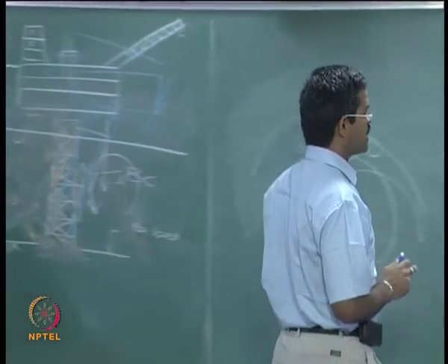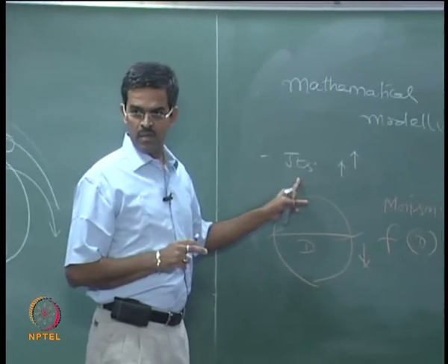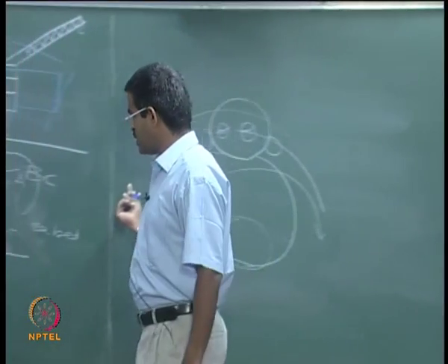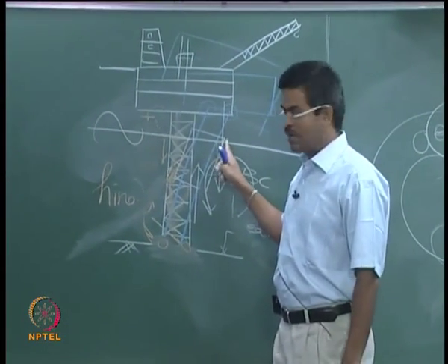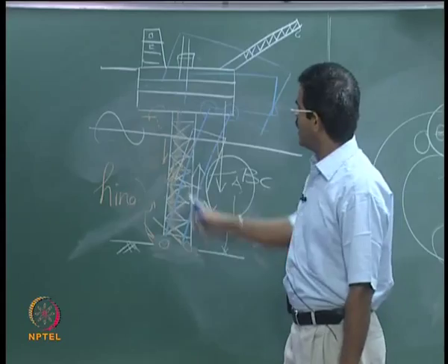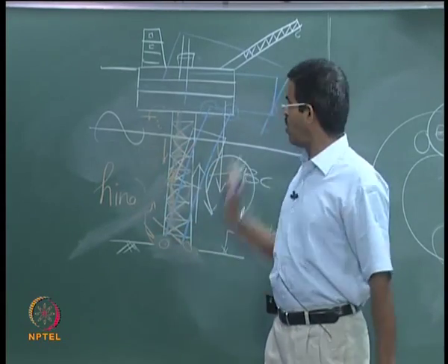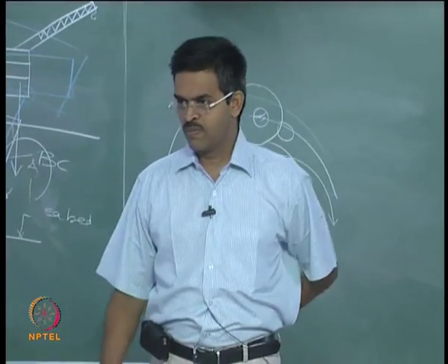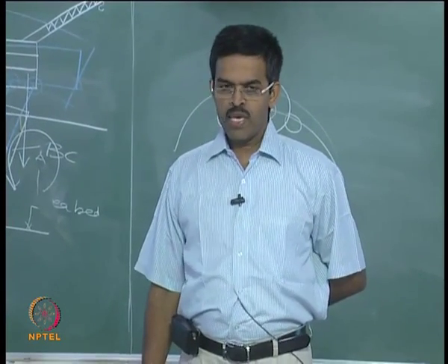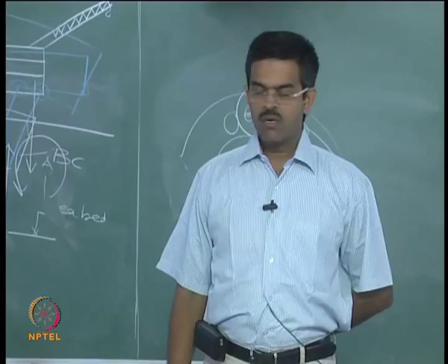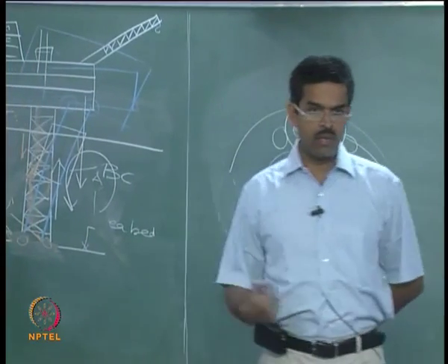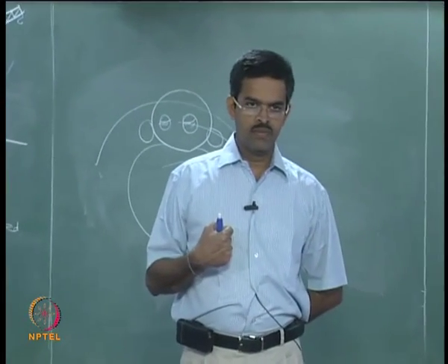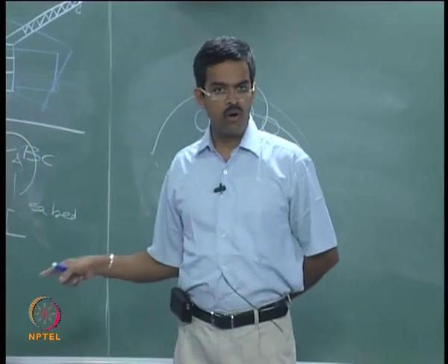So, when you introduce flexibility because of joints, you must compensate this flexibility by some other mechanism like a buoyancy chamber, like a mooring line, etc. All these towers in general are called compliant towers. Why was compliancy introduced? Because I want less force to be attracted on the member, because I want to use it for deeper waters.